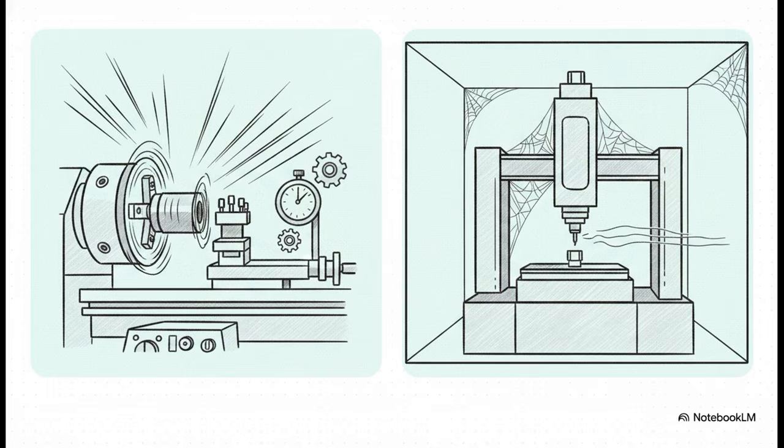So why does all this matter? What's the real business value here? Well, this brilliantly illustrates why experienced engineers absolutely love runout. If you use position or concentricity to control a rotating shaft, a machinist usually has to take the part entirely off the machine, bring it to a climate-controlled room, and set it up on a highly complex coordinate measuring machine, or CMM. But with runout, they can literally just slap a magnetic base and a dial indicator right onto the lathe, spin the part, and verify it in seconds. It is drastically cheaper and just so much easier for manufacturing.